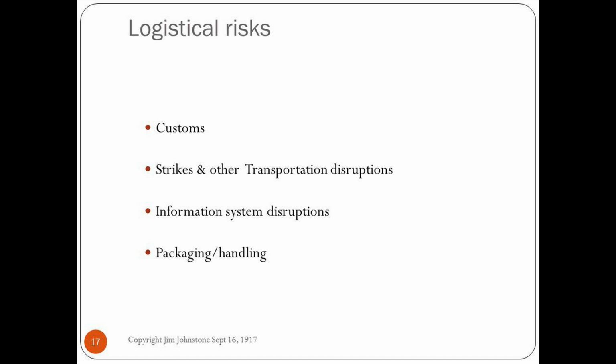Who's responsible for the package design? Usually small suppliers are not capable or proficient in designing packaging, so they have to hire that out. Who does it for them? Does your packaging have to meet any specifications or standards? Where's the supplier going to get the expertise to not only design the package, but get it tested? Are you using any hazardous material that has to be labeled or protected? Is the packaging designed for the handling that it's going to see in the pipeline before it gets to you? These are all questions you need to ask of your supplier and of your engineering team.